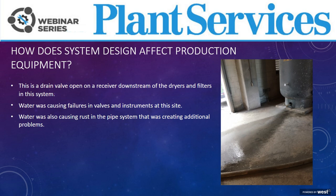In this particular case, you see the water draining on the floor. We went into that plant, opened the drain valve on the dry receiver, on the receiver that was downstream of all of the air treatment in the plant. We drained about 200 gallons of water out of the dry receiver.